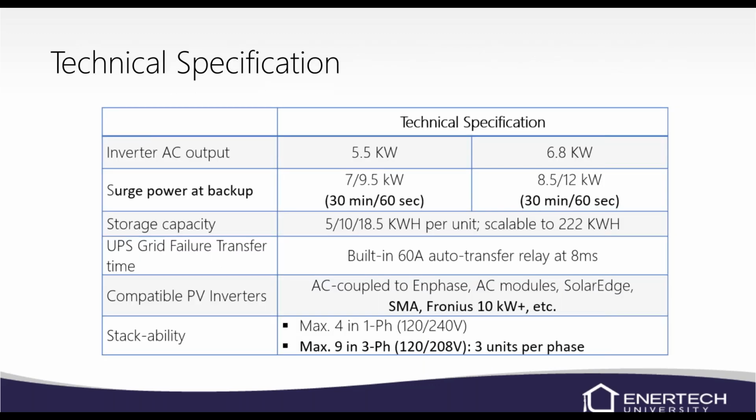Just some technical specs: surge power at backup, storage capacities, stackables, 4 in the single phase, 9 in the 3 phase, and the inverter output capacity. It does have a built-in transfer relay, so it's basically a grid failure transfer switch. And once it sees a grid failure, it takes 8 milliseconds to switch over. So pretty quick.